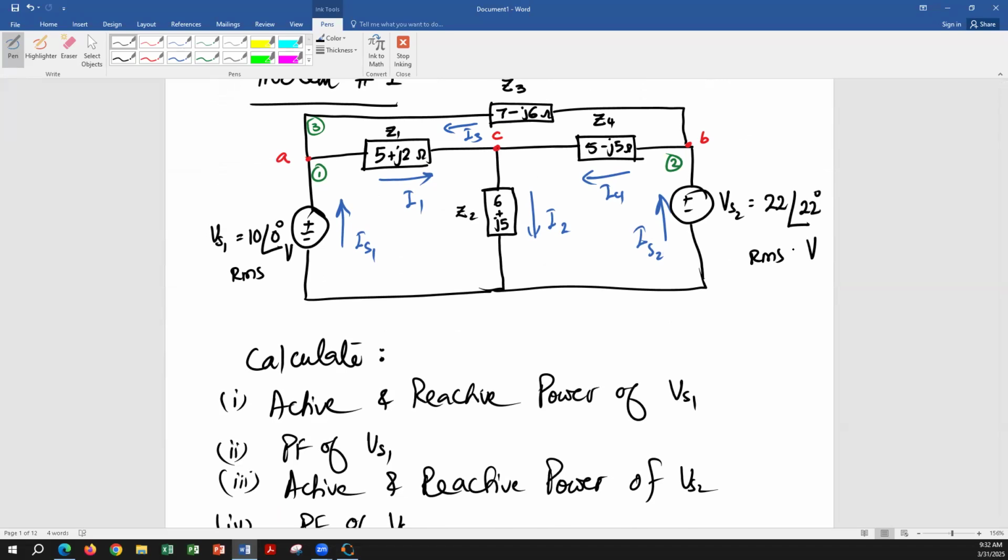Yes. So that's in the beginning when you had first asked the first question, that's why I was thinking to go from 10 to whatever. That's fine. If it is not given, assume them to be peak. And if it is given that they are RMS, then use RMS. If it is given in time domain, then it's always peak, right?